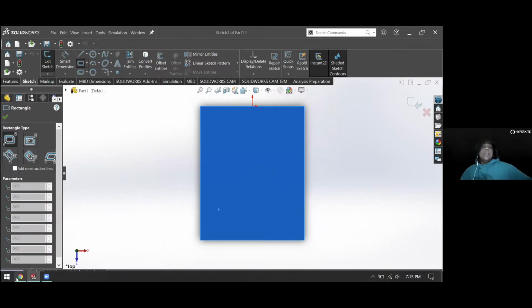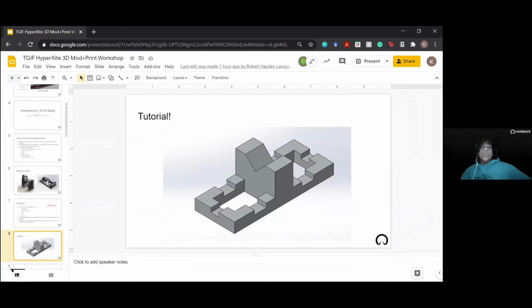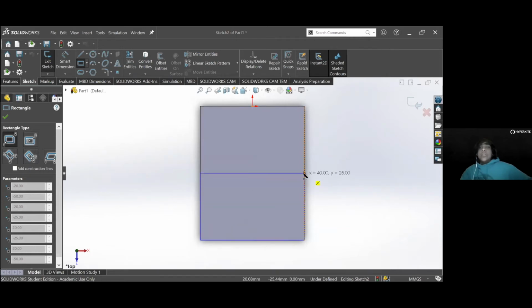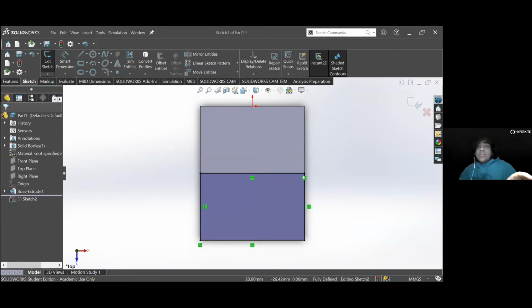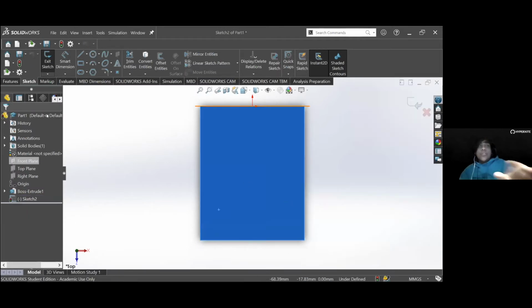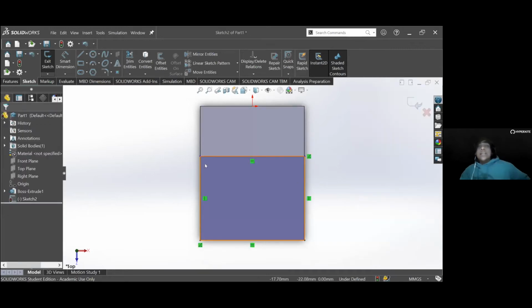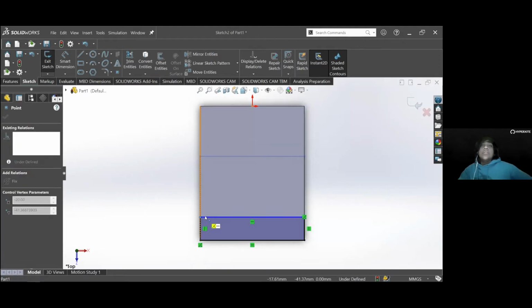Now I'm going to choose the rectangle. I know that the cut is along the edges, so it's open. Since I have a corner rectangle, I'm just going to choose the corner here, and then another corner here. As you can see, oops, I'm just going to Control Z. As you can see, what ends up happening is that I now have a rectangle that's constrained on 3 sides, because it's using the dimensions of this box and saying that these coordinates are fixed to the edges, right? So the only thing left to do is to fix the z-axis.